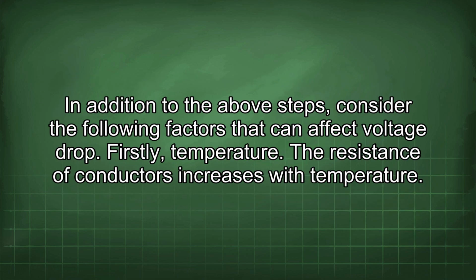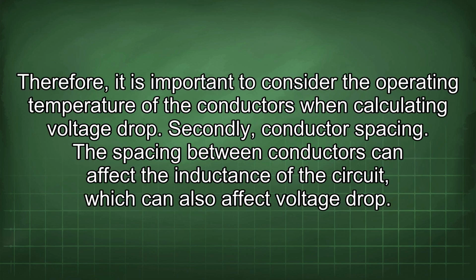In addition to the above steps, consider the following factors that can affect voltage drop. Firstly, temperature. The resistance of conductors increases with temperature. Therefore, it is important to consider the operating temperature of the conductors when calculating voltage drop.